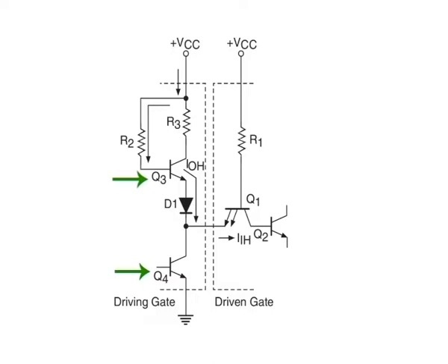Because of the low output impedance, any stray capacitance at the output can be charged or discharged very rapidly through this low impedance, thus allowing quick transitions at the output from one state to the other. Another advantage is that when the output is in logic low state, transistor Q4 would need to conduct a fairly large current if its collector were tied to VCC through R3 only. A non-conducting Q3 overcomes this problem.